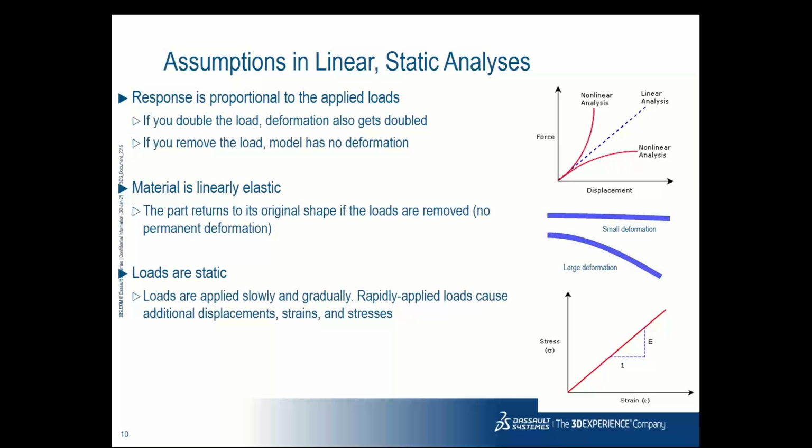So we saw the three basic assumptions that are followed in case of linear static analysis. The responses are proportional to the applied loads, the material is linearly elastic, and the loads are static.